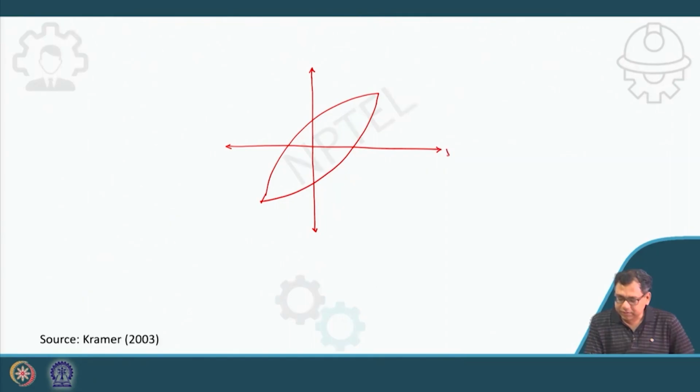So, if you can see, this is the shear strain, and this is the shear stress. The slope of this line at any point is G tangent. And I have already discussed what G max is. G max is the slope at the initial portion of the curve, which gives me the maximum shear modulus. And actually G is changing at every point along that stress strain curve.